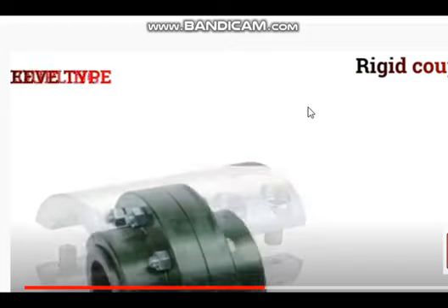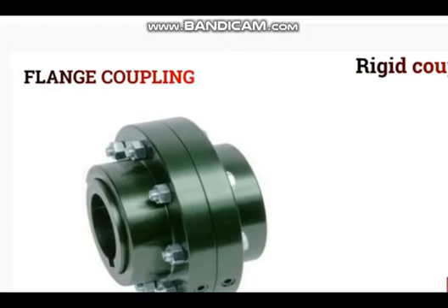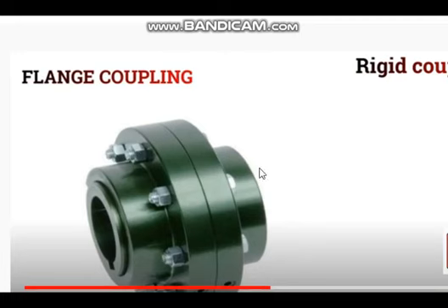And this is a flanged coupling. This type of coupling you may have seen many times. See how many nut bolts are there? One, two, three, four. Here we are seeing it is not even 180 degrees, so maybe another 10 nut bolts are there. It depends upon how much torque you have to transmit. Depending upon that, the nut bolts will be there.